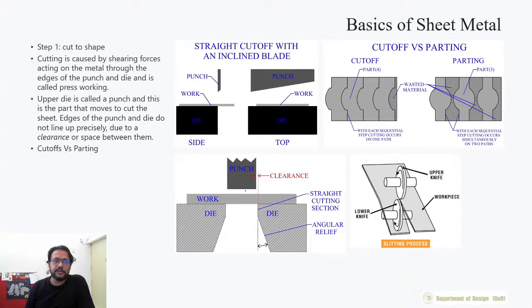Sometimes you don't want a cut, you don't want to shear it. What you want is a circular blank. In such cases you would have dies designed specifically for that. This would be a cylindrical punch, and this is a die. The punch would come down and cut the material from these sides, and you would use either this part or that part, whichever is important.